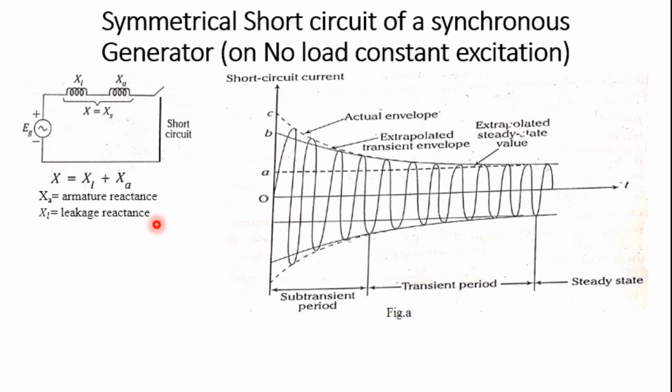We know that in the case of a transmission line, which was discussed in the previous concept, the armature current will have an AC component as well as a DC offset current. This will be different in each phase and is accounted for separately on an empirical basis. Usually the multiplication factor will be around 1.6.